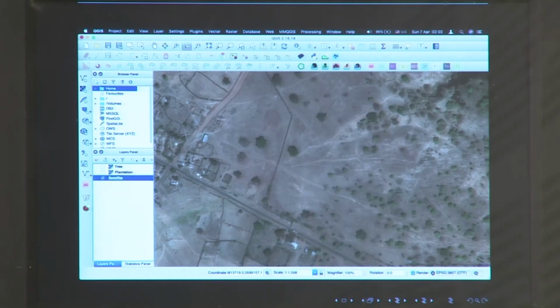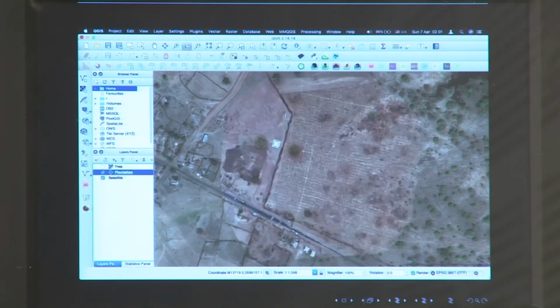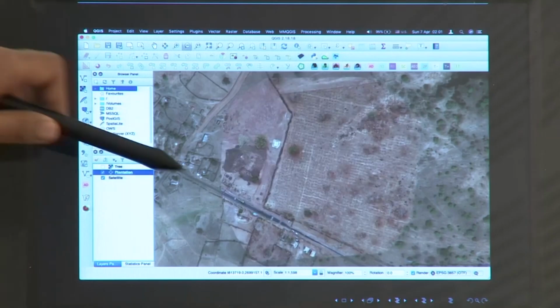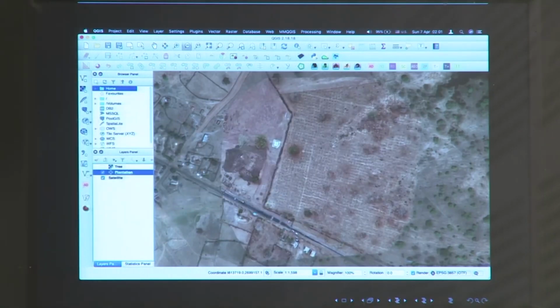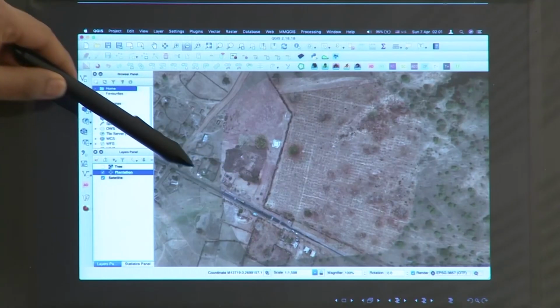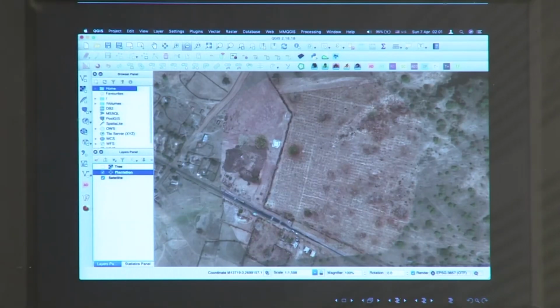So, in the previous image you have a plain road, and now in this image you can see that here the road has thickened and here it is a single lane road. So, probably this road was expanded after the satellite image was taken. So, now you are using photogrammetry to interpret different locations to get an idea of your area.